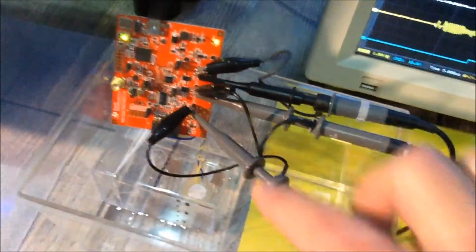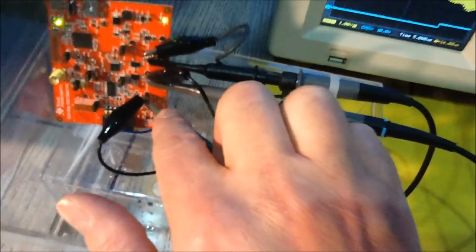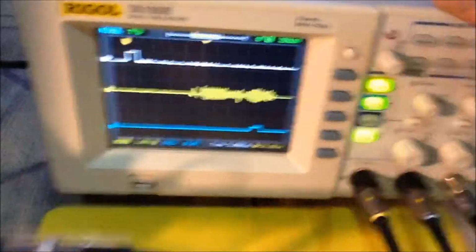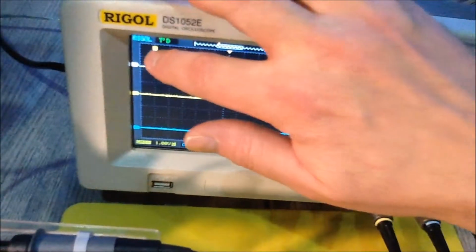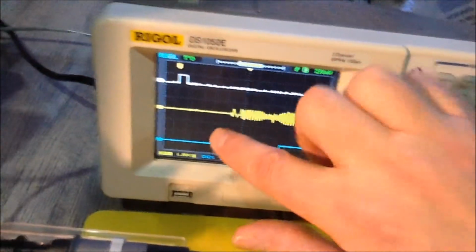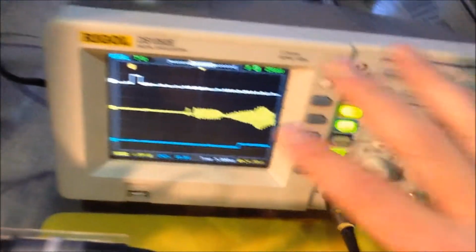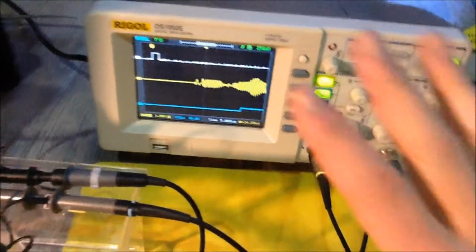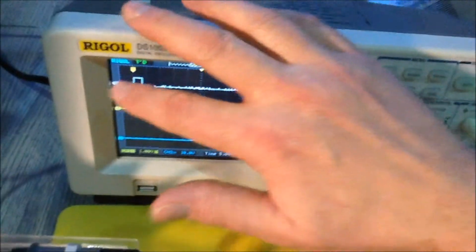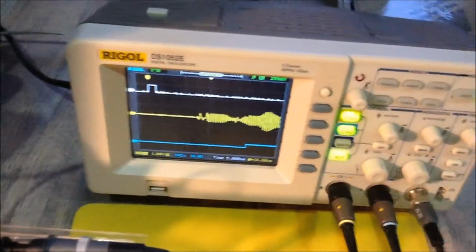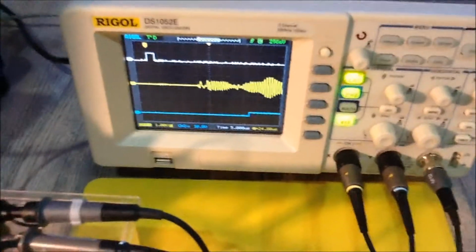Voila, I've done that. The A signal is now connected to the composite signal from the piezo element, and you can see that the memory stays where it is, and that's actually the trigger point, and we can see that analog signal. So everything that we wanted is done. We have 3 signals on a single scope. It only works if that signal is repetitive and stays on a fixed position, and that was the case here.